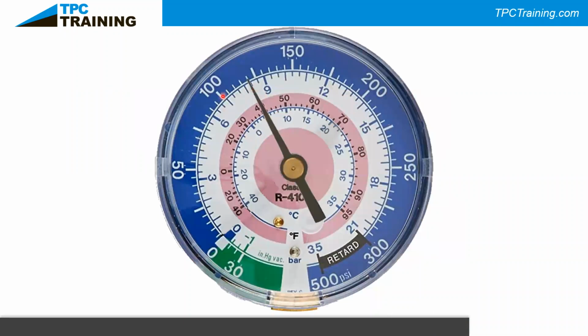So if I have 0 going up to 100, these small lines in between represent an extra 5, 10, 15, 20, and then 25 would be in the middle between the 150 and the 100. At 120 PSIG, if you were to look on a PT chart for R410A, you would see a saturation temperature of 40 degrees Fahrenheit. That's what we're showing you on this gauge, where it crosses this line, a built-in PT chart range here. And for those in Canada who read centigrade, it would be approximately 5 degrees Celsius.